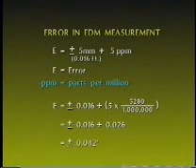In this example shown here, we have measured a line 1 mile, or 5,280 feet long, with an EDM. The total error for this line would be equal to the plus or minus 0.016 foot error found in every measurement, plus 5 parts times the ratio of 5,280 to 1 million.